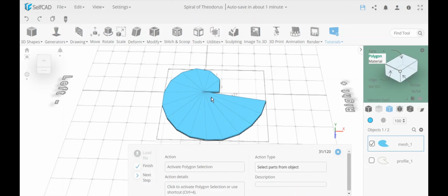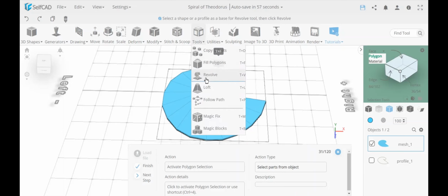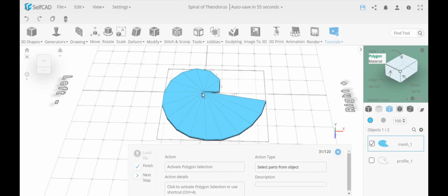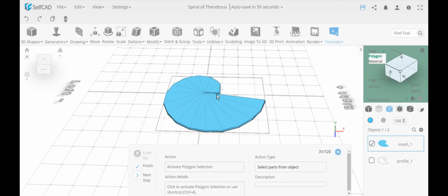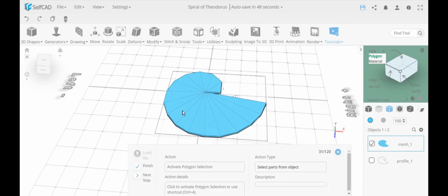But nevertheless, the idea here is that every vertex you give it must be used. It cannot leave out any single vertex, and it can also not add another vertex. Meaning, if you have some other, more parametric modeling tools, for example the loft tool, it's going to interpolate if it needs to. It can add curvatures, it can add additional vertices. In this case, it works totally differently. But when you think about a constraint triangulation, everything works depending on how your structure is.